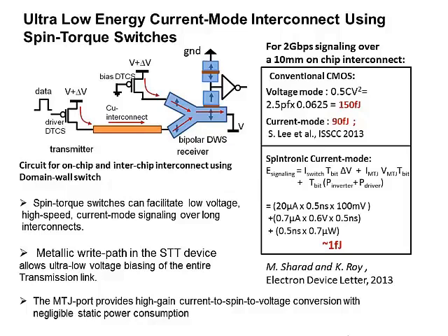Since the write path of these devices is a very low resistance metallic path, once again we can bias the whole interconnect link at a very small terminal voltage of the order of few tenths of millivolt, and as a result, although we are using current mode data transmission, the static power consumption because of the current mode data transmission is very much reduced. At the same time, the magnetic tunnel junction formed with the free layer can be used to detect the spin state of the free layer without incurring any additional power consumption.